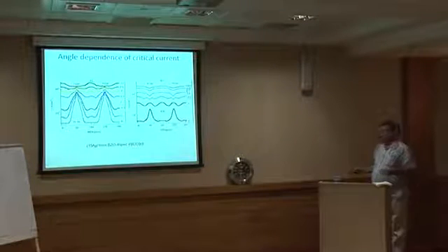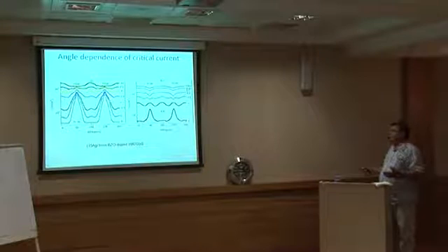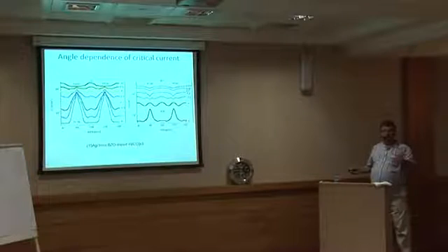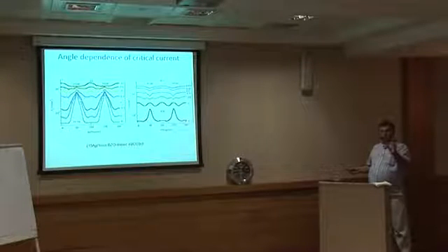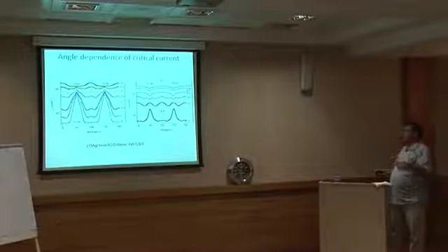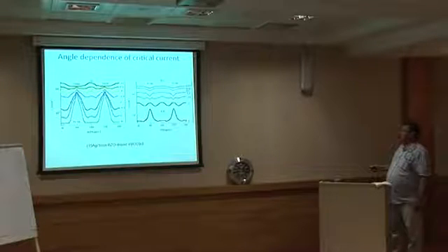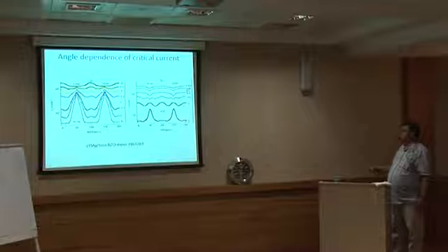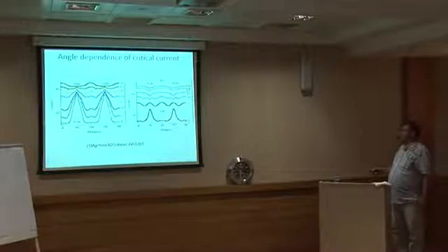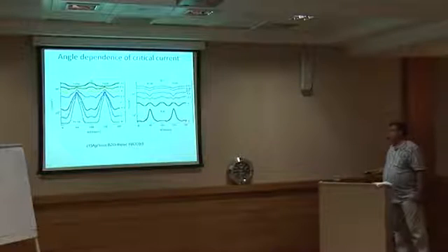So for an application in which you expect to have 2.5 Tesla, if you put 10 to the 5th amps per square centimeter, then you are sure that it doesn't matter what the field orientation is, you will not subject a piece of your equipment to current larger than its critical current at that orientation. Now, if you move to higher fields, of course, you will go back to the normal situation in which the critical current is larger for field parallel to the AB plane.